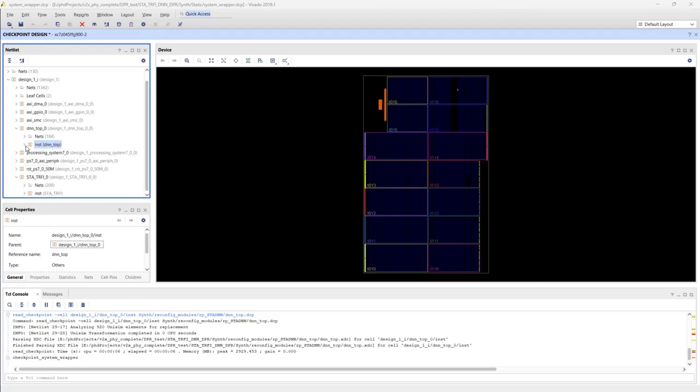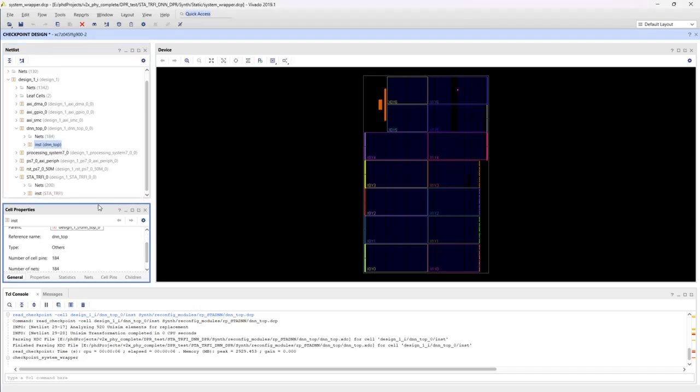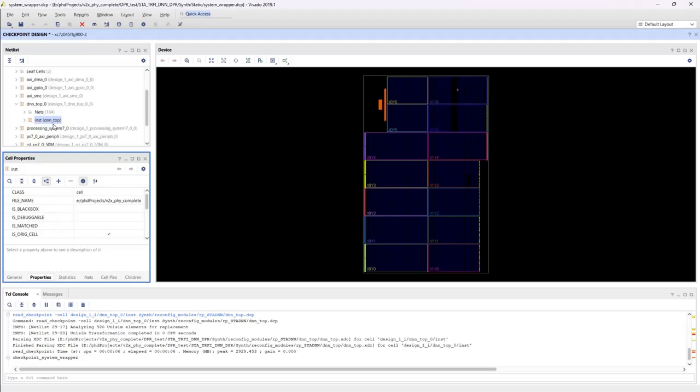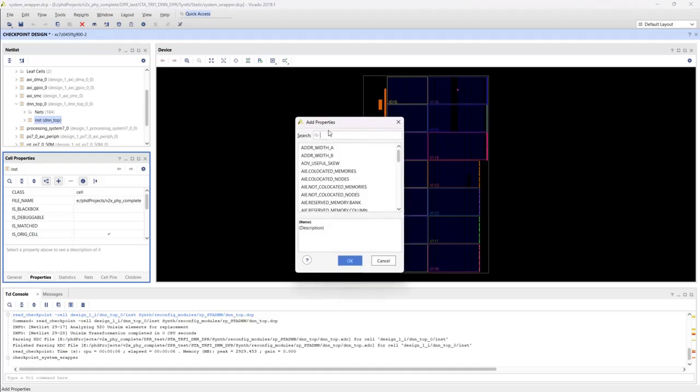that we select it. All right, and then we go to these cell properties. Okay, the properties here, and we have to make this reconfigurable. Now these two instances, these two cells, we have to tell the tool that they are reconfigurable. For that we need to add this property in here.